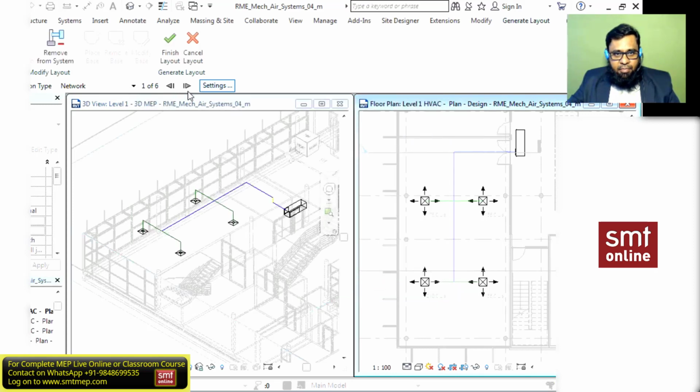And after this, here we can go for the different option. You see 1 of 6 solution. So 1 of 6 is straight and turn with the branches, and the second option in this way. So like this, which is best as per the site condition or as per your experience, we can click finish to convert this into duct. So this is also a very useful option to save a lot of time to get the auto routing for the ducting and auto routing for the piping.